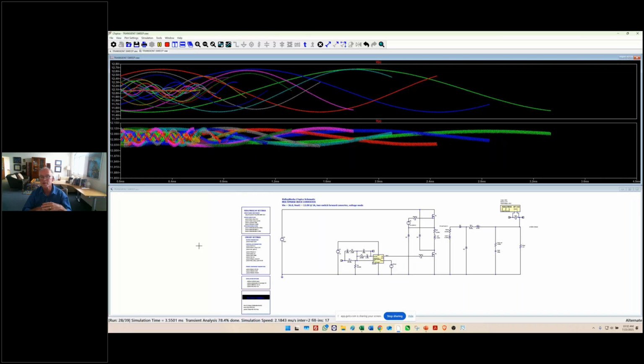Okay, so we're sweeping through this model here. We're almost done, 33. Now, don't try this with complex models for your FETs and complex models for your controllers and complex models for your transformer. The more complexity you put in, especially in the semiconductors, the slower this will run. So you start establishing the fact that you've got to have different levels of your simulation models to make this all work. All right, it's all finished.